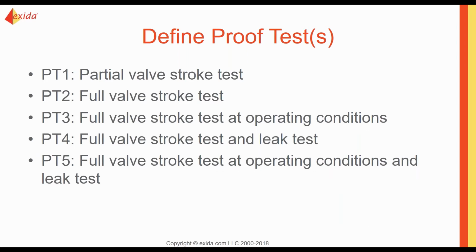Then as we're still in the design phase, in the SIL verification, we're going to assume and model proof tests, and depending on what proof test we're using and what diagnostic we might be using, we're going to have different coverages.